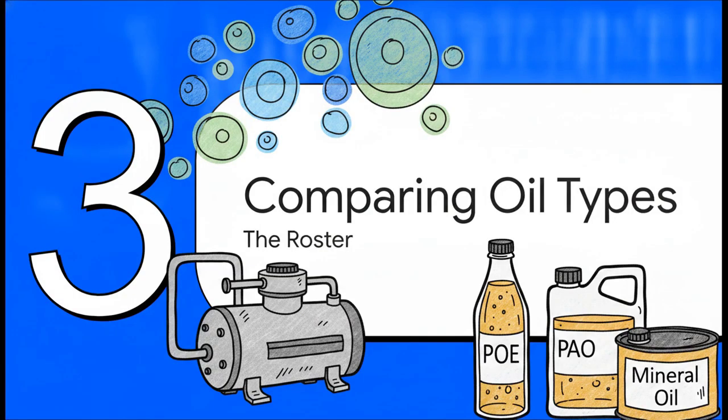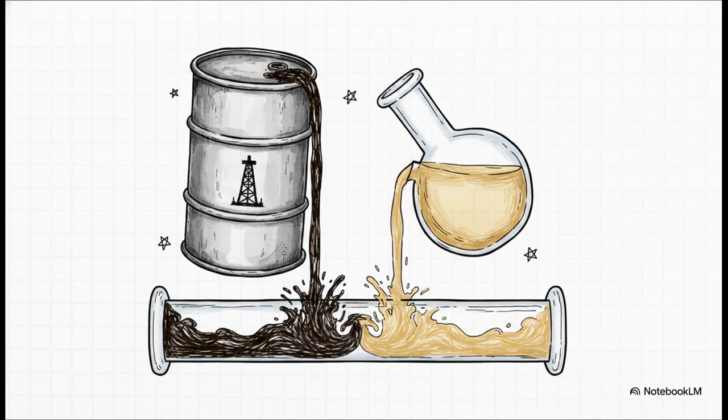Okay, Section 3. Let's compare the actual types of refrigeration oils. Let's look at the roster. We'll kick things off with the traditional oils, mineral oil and alkylbenzene. Mineral oil is your classic refined petroleum product. It's stable, it's low cost, and frankly, it forgives a whole lot of sloppy field practices.